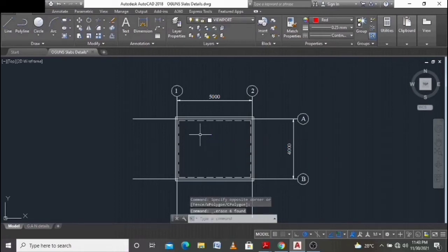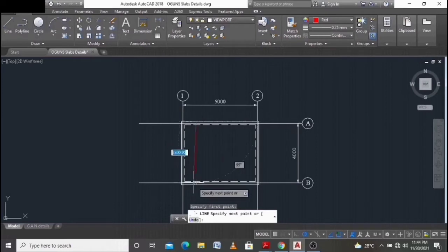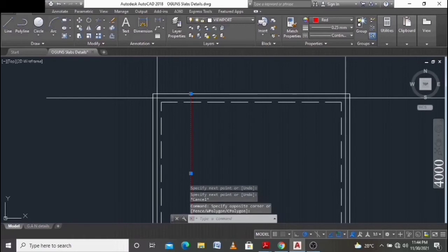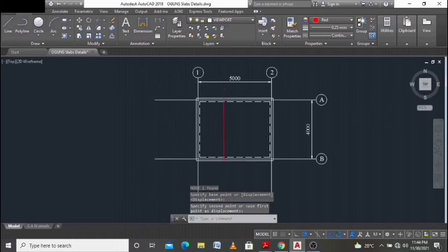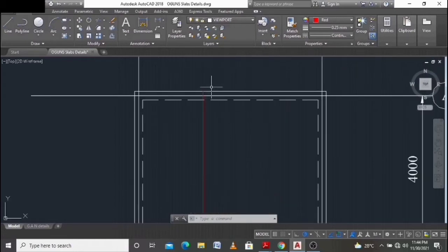So we know that for a slab, the main reinforcement spans along the longer span rather, where it spans along the longer span. So we have the reinforcement coming this way. So this automatically becomes our main reinforcement. But mind you, your reinforcement cannot be like this. Yes, there ought to be a provision for cover and anchorage also.